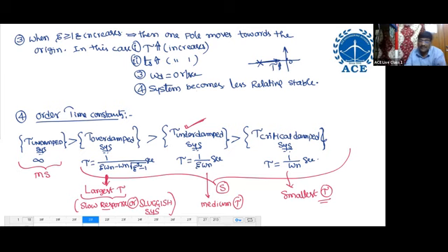Generally, the best range of zeta is between 0.4 and 0.7. We don't select even very close to 0, or very close to 1. It will come later. Why is the underdamped system most preferable? That will come later.